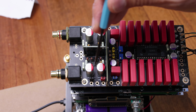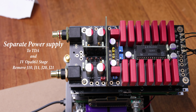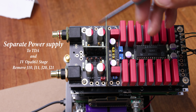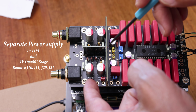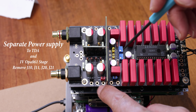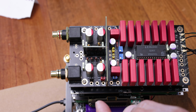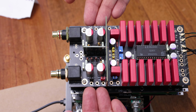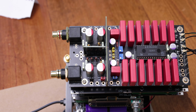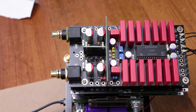And then we have a couple of jumpers here. This is for the IV stage, for the OPA861. This is like your preamplifier stage. So if you want to give this part a separate power, you take those jumpers out and you give it here +5, 0, and -5. So you pull all the jumpers out, and now you basically provide separate power for the left, separate power for the right. These are all great and amazing. I think if you can do that, sure, go for it. But just bear in mind, every time you do that, you're adding more power supplies.